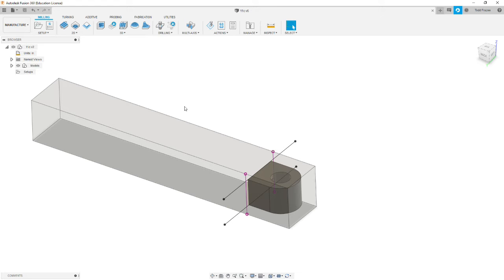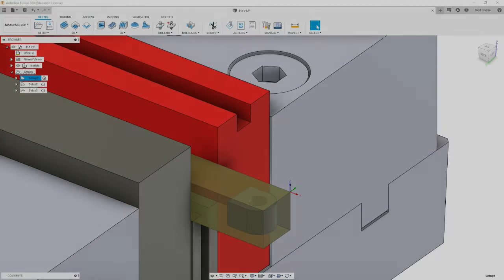If I were to cut multiples of these parts, I would probably have a longer bar and keep advancing the bar to the right for every part we cut, using some sort of work stop that would touch off on the end of the part. This rendering is to help you visualize how the stock would be held in the vise for this operation.